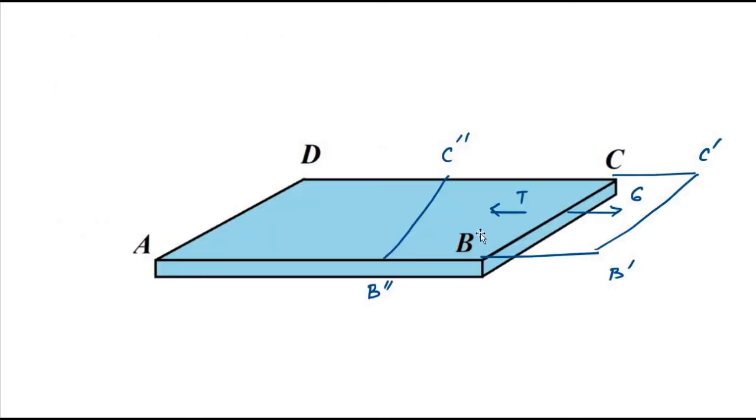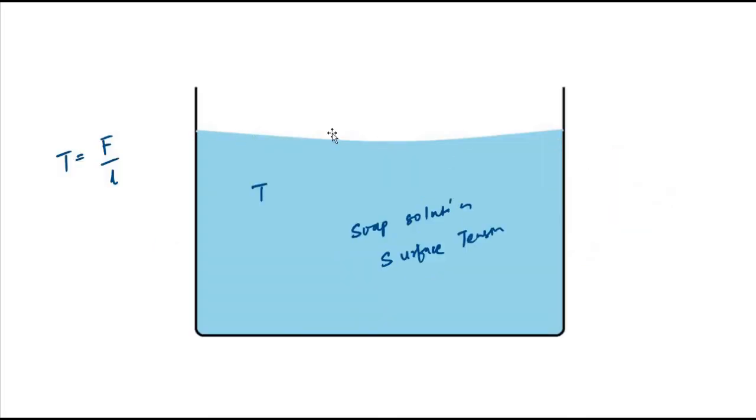Surface tension and surface energy have the same magnitude and the same units, but the direction in which they are applied is opposite. Surface tension tries to reduce the surface area by pulling the top surface of the liquid downwards. Surface energy tries to push it upwards, opposite to the direction of application of surface tension.